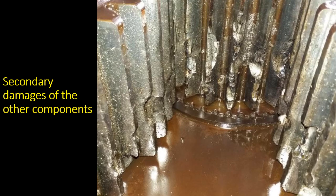The next point to consider is secondary damages of other components. So let's say a defective gear in a gearbox can damage its mating gear, and a faulty bearing in a gearbox could result in improper loading on the gear or misalignment, which could cause the damage of the gear. Similarly, a faulty bearing could damage the shaft, seals, etc. An excessive imbalance could damage your bearings, which in turn could damage your housing or shafts, and so on. An excessive misalignment could damage your coupling, bearing, and seals. So you can consider all these secondary damages and you can calculate the cost involved in the spare parts.